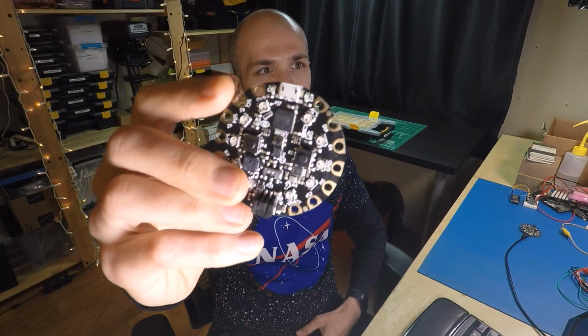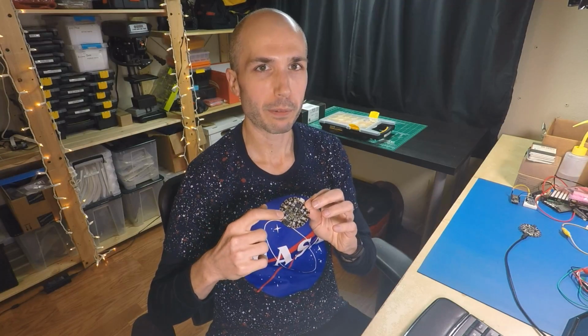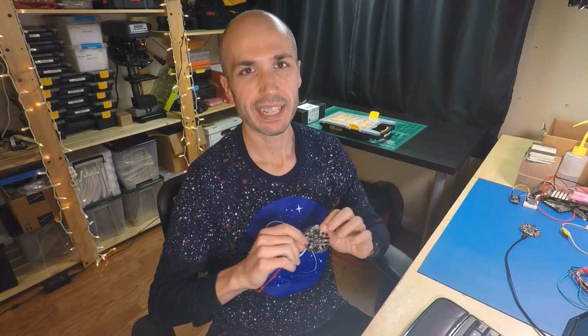And the cool thing is all of the pads on the outside here have capacitive touch sensing built in, where you can touch them with your finger and that changes the capacitance that the board detects, and it can tell when you touch it and when you don't touch it. You might remember the old lamps from like the 80s that you would touch the base of the lamp and it would turn on. It could detect when someone touched it, and that's again using capacitive sensing.